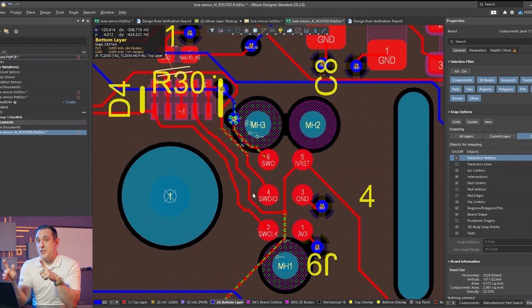Now, one of Matthias' questions that he asked in his LinkedIn post was whether or not this routing or this layout would be functional. And a lot of this weird routing would actually be perfectly functional. But that's kind of beside the point. The point is that this weird routing arises because of really poor placement, and the poor placement creates its own set of problems that aren't dealt with routing.